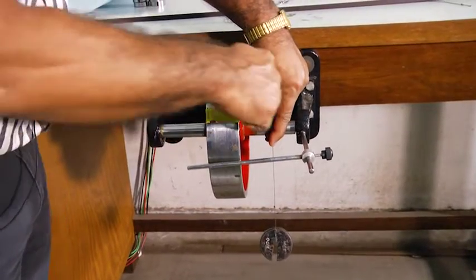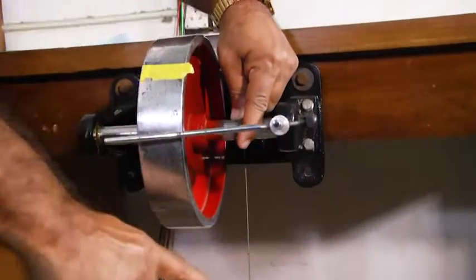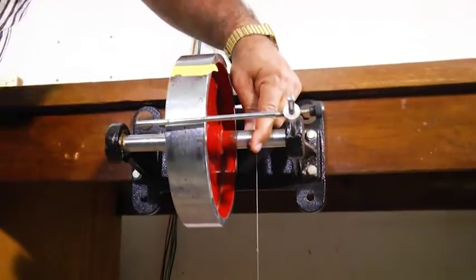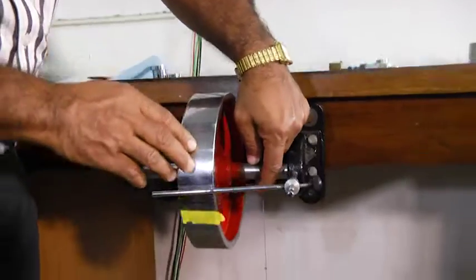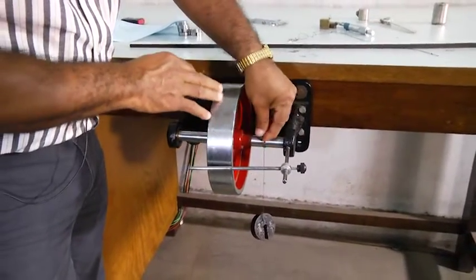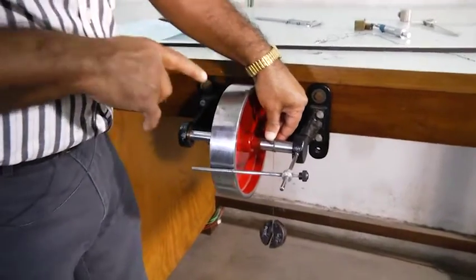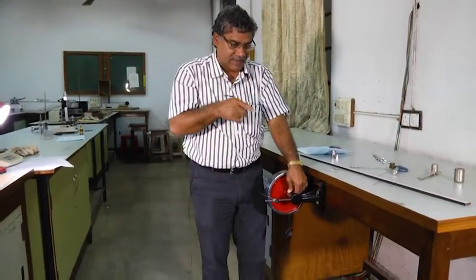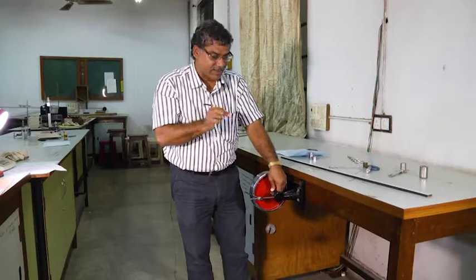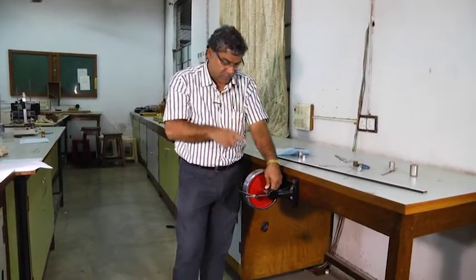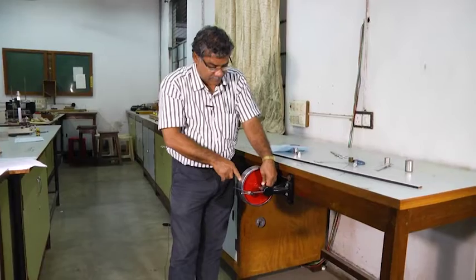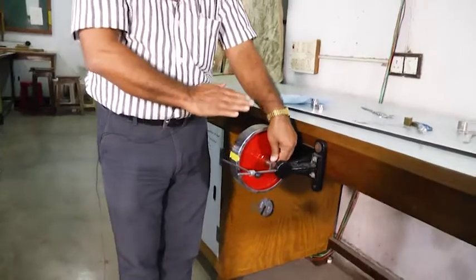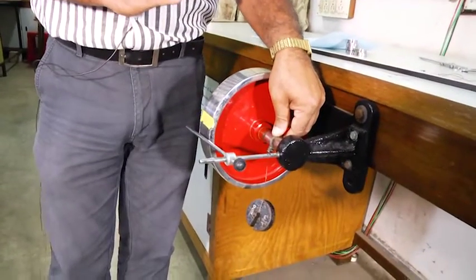So, here when it will touch the floor, then it will turn 10 times, right. It will just rotate 10 times. So, for each turn it is F, then for n1 turn, that is what we are telling, n1 turn. For each turn this energy dissipation will be there. So, that is n1f basically, in theory I told you. This is the meaning of n1. My position was 10 turns, so this n1 we are taking, this reading is 10.